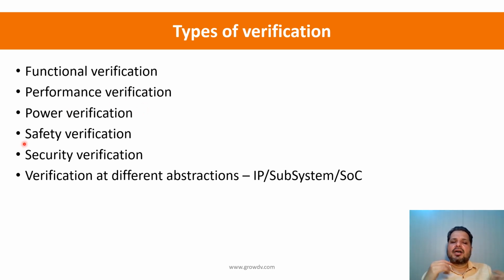And these days, with the growth of usage of silicon in the automotive sector, safety verification has become very important. And as a part of safety verification, what they try to check is that if a design develops some sort of a flaw due to usage over a period of time, can we detect that flaw and report it, and then put some redundancy such that if there is one part of the design misbehaving, it can switch over to another one to make sure that there's no critical failure for the critical parts of the logic.